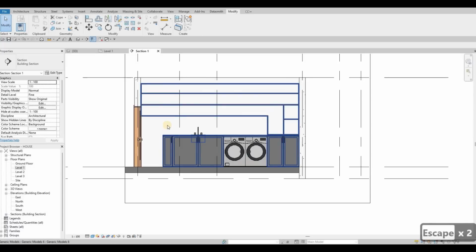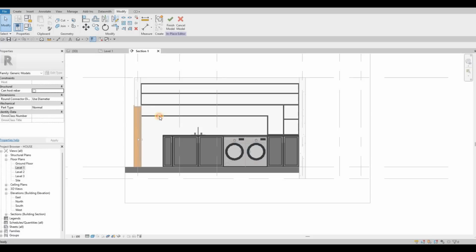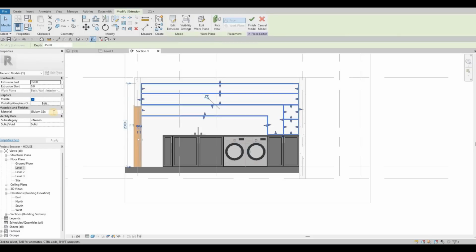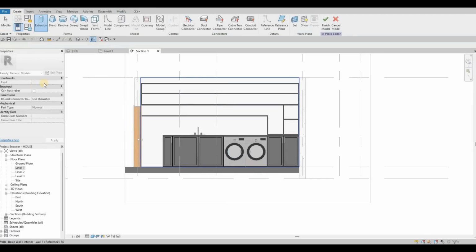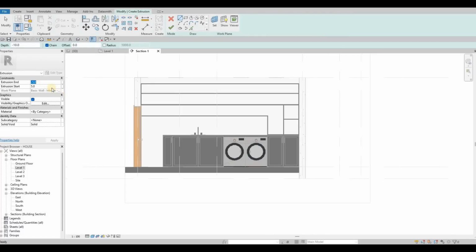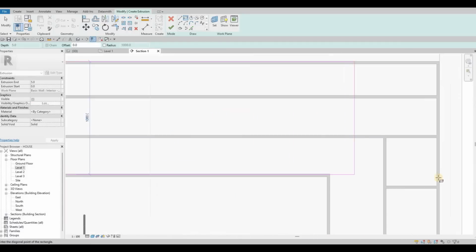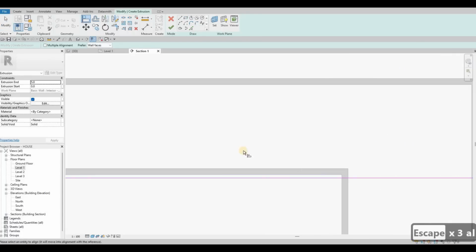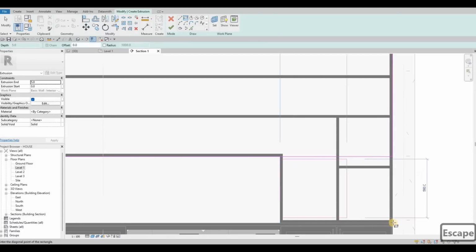And then what I'm gonna do is I'm going to add some backings here. So edit in place. I'm gonna add this material as well. Extrusion, pick a plane, and I'm gonna select the wall, and I'm just going to put 5 and then 0 here. And then let's just add the background here, align it here, and then here as well.